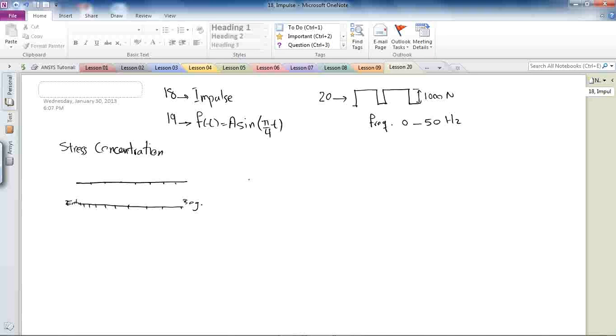The other thing that is interesting in meshing a sample is, let's say we have a point which is a stress concentration point for us in this model. Imagine a crack in a sample. So I want to show you how you can define a stress concentration point on your model. So basically the simulation I'm going to do will be very similar to the fracture mechanics concept.